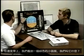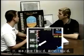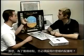Okay. On the speed tape, we have a little green circle, which we call what? Green dot. And what does green dot represent? Well, it's basically L over D, the best L over D, but it also represents ICAO holding speeds as well as our drift down speed. Okay. And what kind of configuration would you have to be in order to get green dot? You have to be clean.